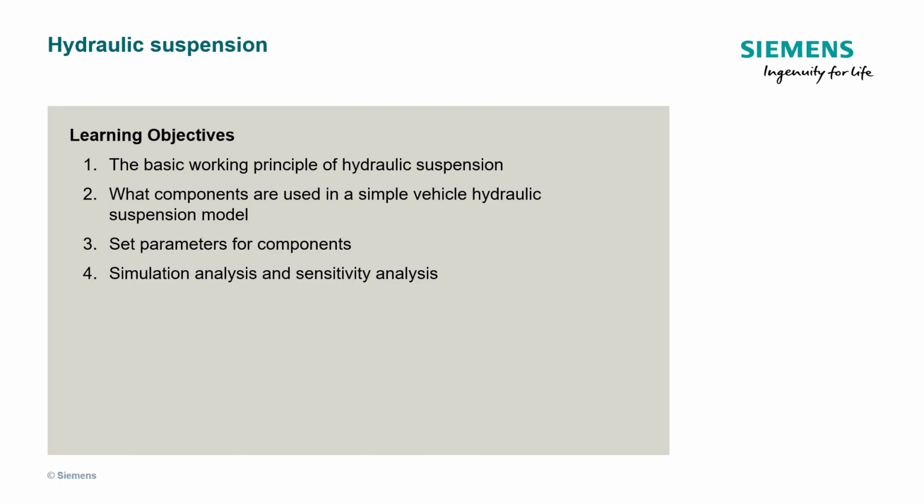The second, we will show you what components are used in the simple vehicle hydraulic suspension model. The third, we will show you how to set parameters for hydraulic components. And finally, we will run the simulation and analyze the results, and change the diameter of orifice for sensitivity analysis.